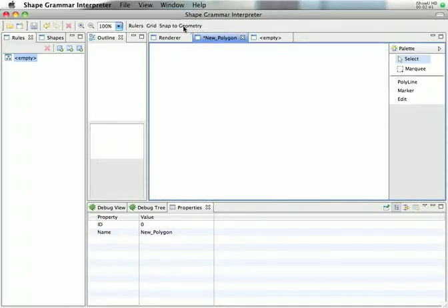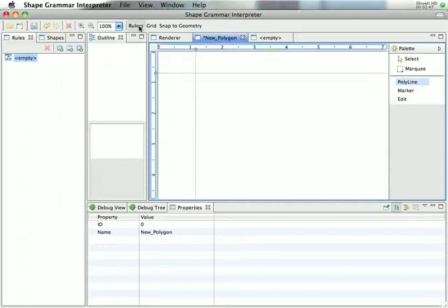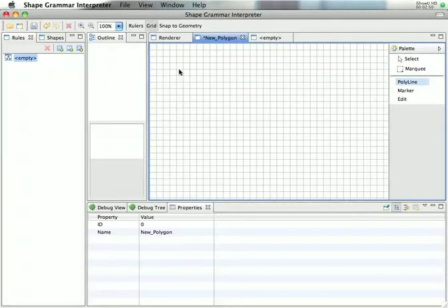Let's now go step by step. We turn everything off, and we want to create, for example, a new square. Creating a square would be nice using the grid, because by snapping to the grid points, it's easy to create a square. Again, to finish the addition of the shape, either we navigate the line to the start point and it immediately closes, or, for open shapes, we hit enter to confirm, or we hit escape if we don't like